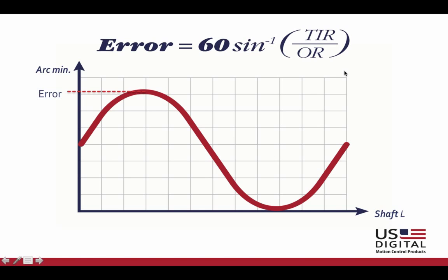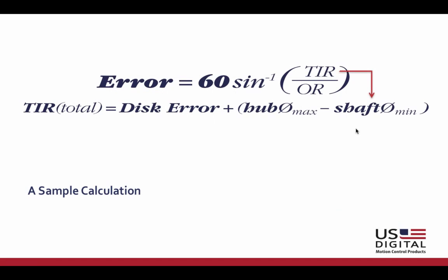In this situation, you can see that the gap between the sensor and the disc is not represented in the equation in any place, so it's really not an error component. Of course, the gap between the sensor and disc has to be within the manufacturer's operating conditions to maintain a stable signal. If you get outside those conditions, all bets are off, of course.